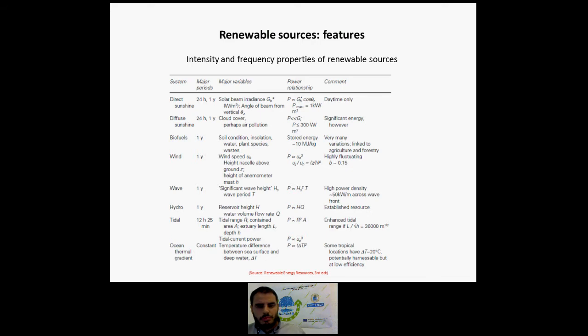Well, the proportions are typically for wind more or less 35%, for hydro 80%, for wave about 30%, and tidal range about 60%. Well, these proportions relate to the capacity factor and load hours of the devices, and we will see those factors a bit later in this presentation.